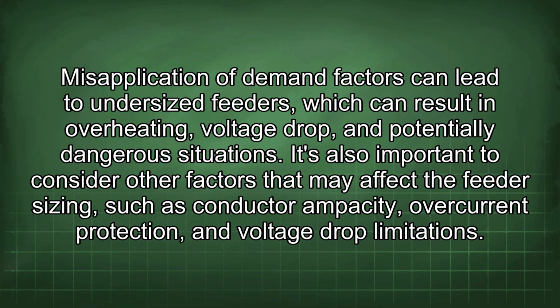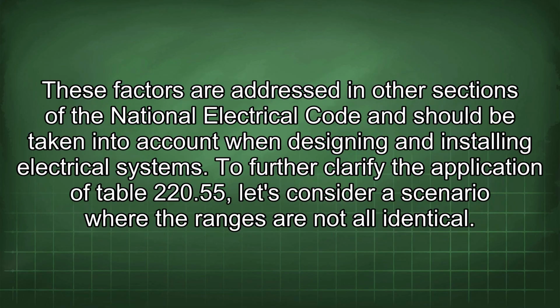Misapplication of demand factors can lead to undersized feeders, which can result in overheating, voltage drop, and potentially dangerous situations. It's also important to consider other factors that may affect the feeder sizing, such as conductor ampacity, overcurrent protection, and voltage drop limitations. These factors are addressed in other sections of the National Electrical Code and should be taken into account when designing and installing electrical systems.